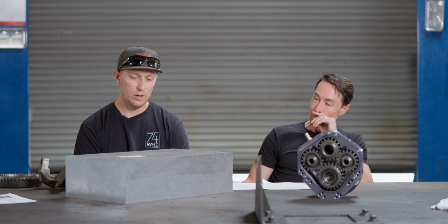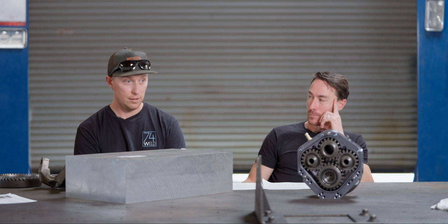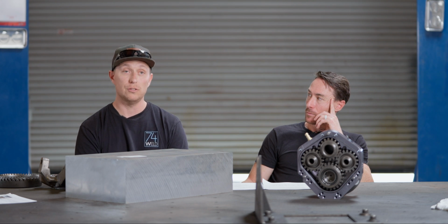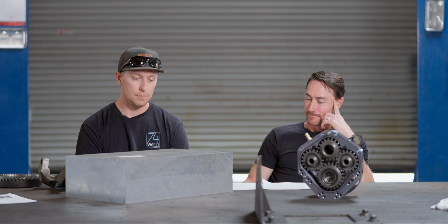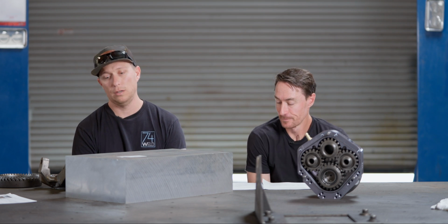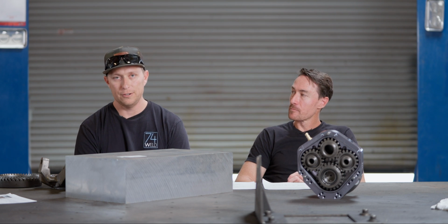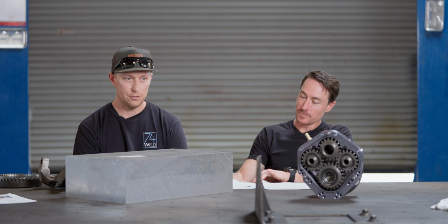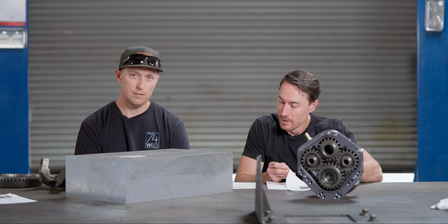And what you're doing, so pretty much every metal, when you get it from a mill, it's been poured, and then as it solidifies, it crystallizes into structures called grains. And when you cold work it, basically what you're doing is creating a finer grain structure and aligning the grains, and that's going to work harden it and give it different properties.